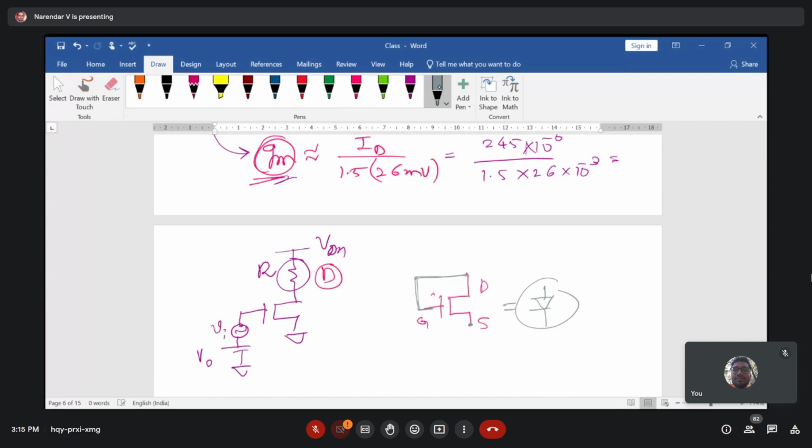Right, so now you can replace this component here and try to analyze the performance of your amplifier, because this MOS transistor doesn't require more area to fabricate and it does not dissipate a lot of power. Okay, so some of the problems can be compensated or minimized by taking this diode connected MOS transistor, acting as a diode connected device, but it is a MOS transistor. That is the MOS transistor based diode connected load that you have to replace it with.